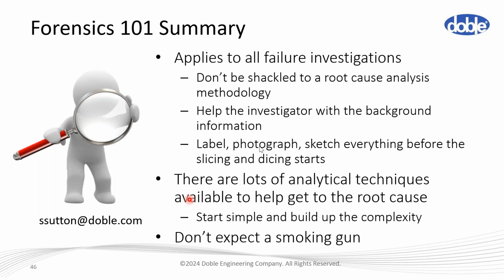which talks about the different types of cables, what you might want to do to them, the pros and cons of different maintenance methods. Also, because CIGRE did a big survey at the time, there are some statistics in there on who's doing what. So what percentages of utilities who responded to the survey are doing, say, sheath testing or insulation resistance testing or VLF testing.